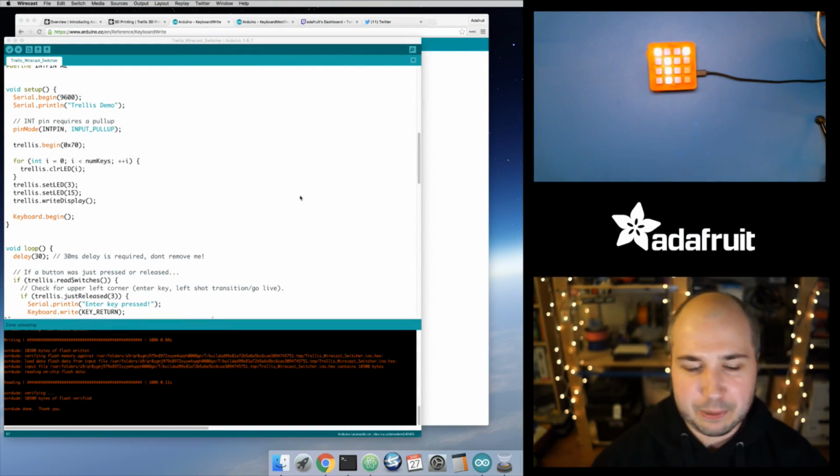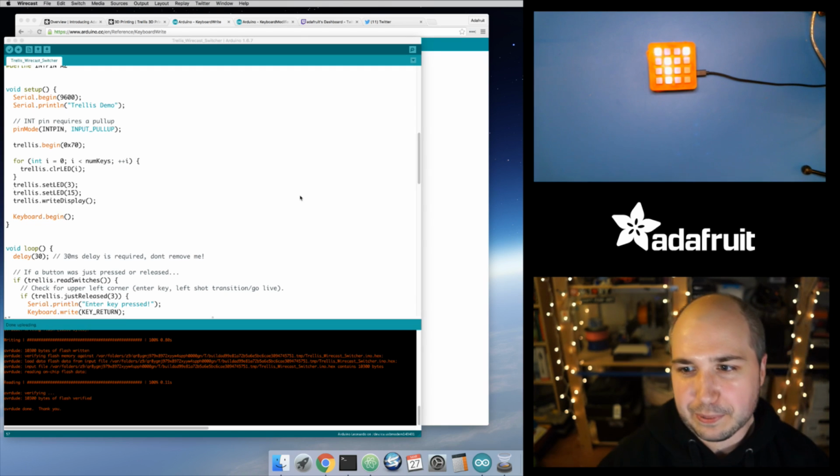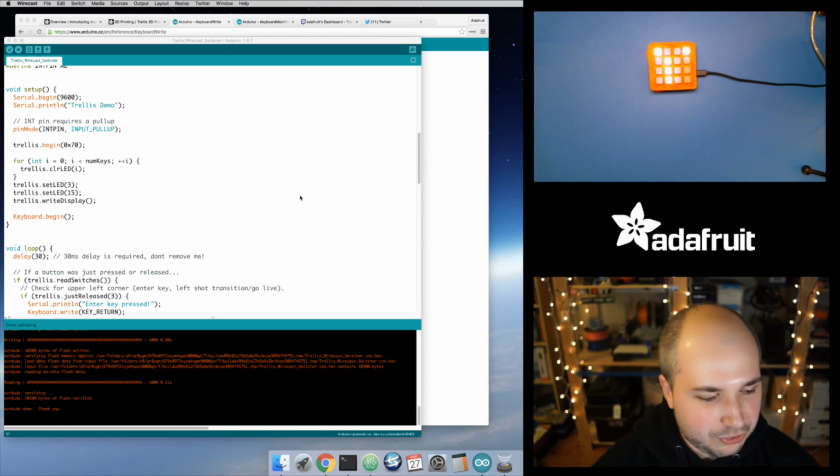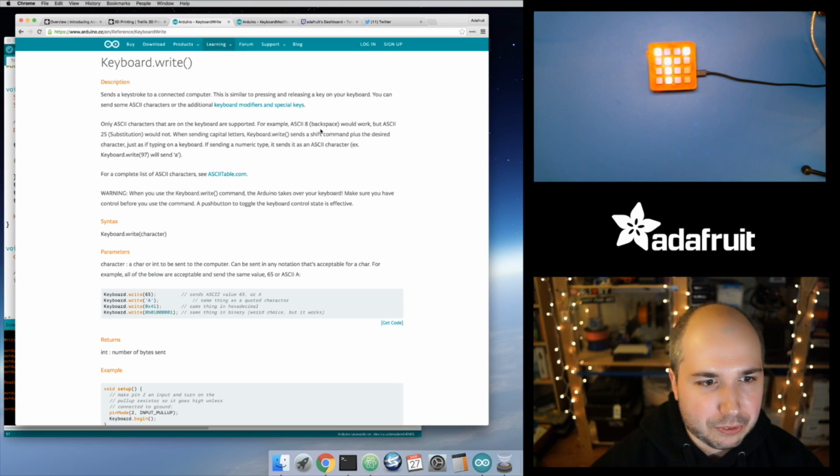Just a quick little project I wanted to do to basically show, here's a real simple way. If you have a program that you want to automate in some way, the Arduino, the 32U4, like the Leonardo or the Feather boards and things, they're a great option to use for that. Super easy to use, the Arduino keyboard library. It can also emulate a mouse. And I think there are other human input devices that it can also emulate.